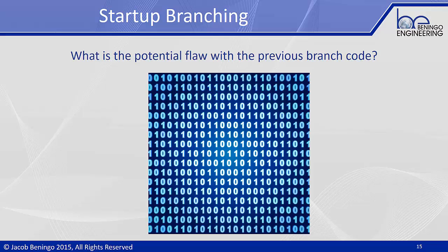So, as you can imagine, there's a number of things wrong. But one of the biggest problems with the code on the previous slide is that we just blindly assume that the application reset vector has been programmed. We're basically assuming that the application exists in flash space when what could have happened is that we have loaded the bootloader onto the microcontroller and we never put the application code, and now no one's pushed the push button and we're going to try to load code that doesn't even exist on the system.